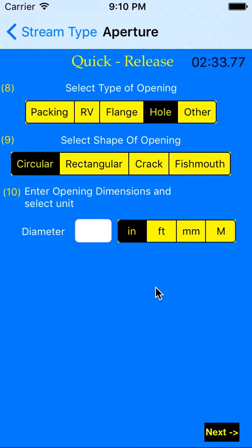And then it's going to ask you for the dimensions. Now, for a gaseous leak, you really want to try to use inches for your dimensions. If you have a gaseous leak and you use dimensions in feet, for example here, then the quantity calculated is going to be quite large.